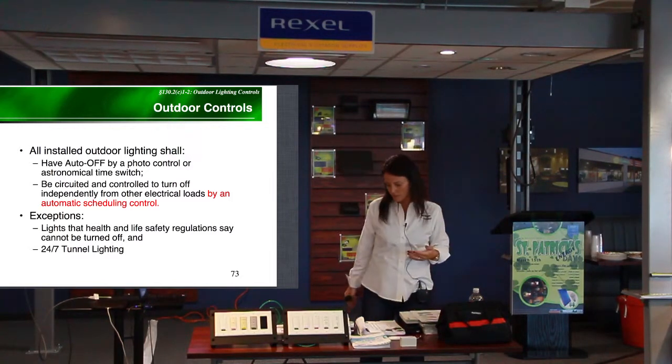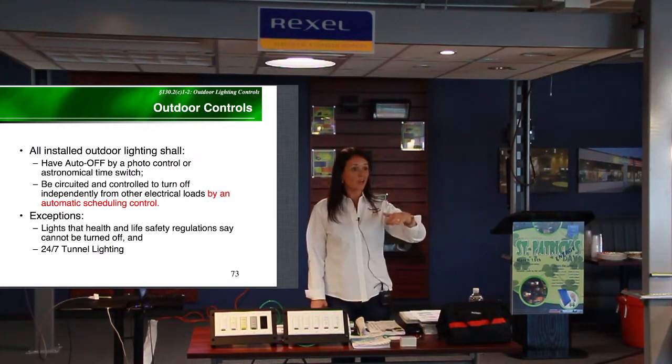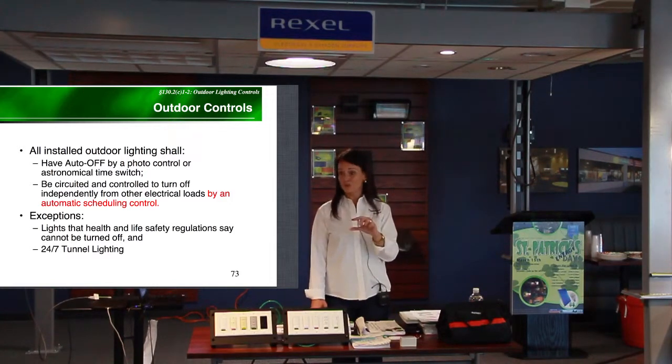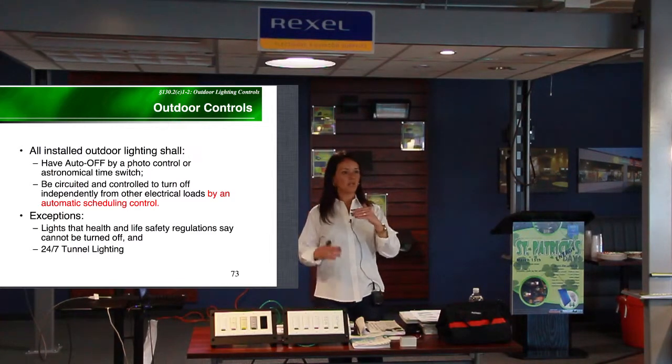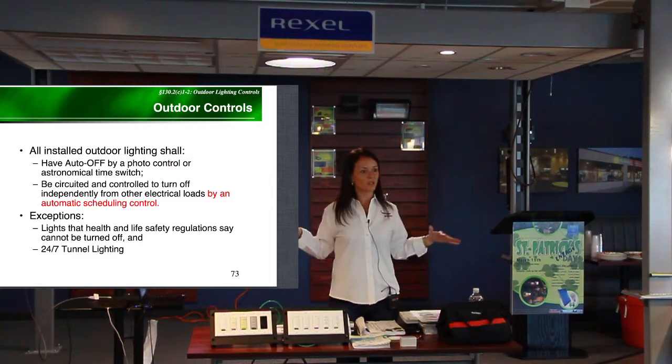So I think I'm seeing more LED fixtures being mounted outdoors with high-low type of controls. The beauty of LED and the 0 to 10 volt drivers is that you can go all the way down to 10%. Depending on the quality of the driver, you can go even lower than that, and it's still uniform enough for life safety.